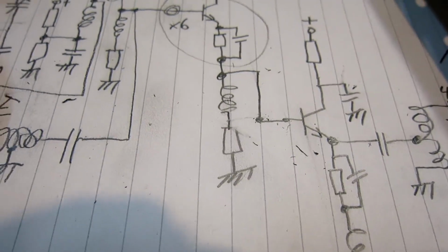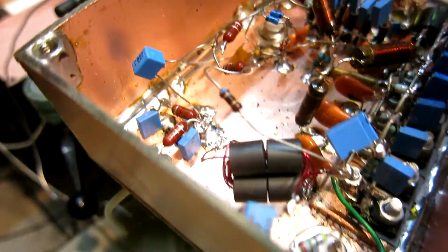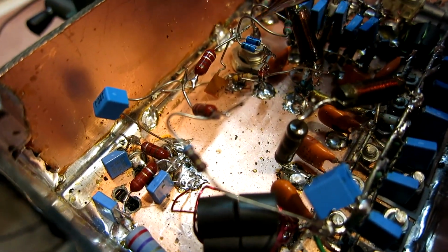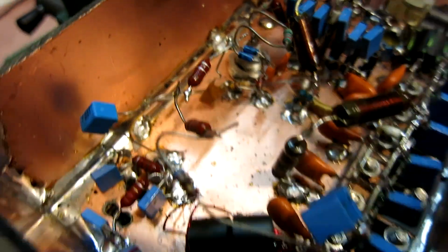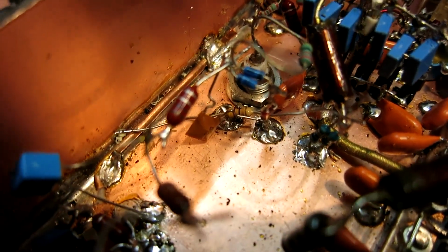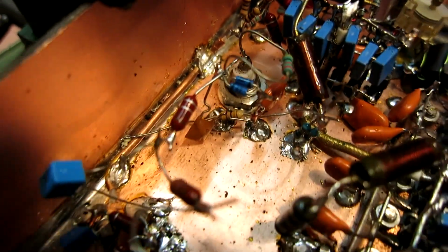I have reconnected the power transistors and added some components: resistor, inductor, capacitor, inductor, diodes, capacitor, and a resistor. That is to provide an amplitude-limited signal of a suitable level to feed into the amplifier input.